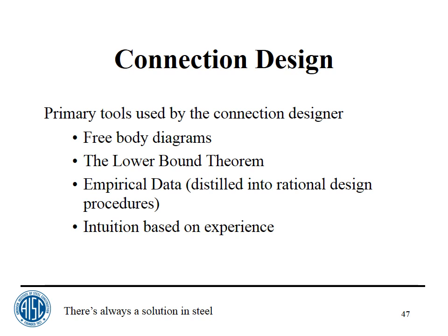So, connection design. The primary tools used by the connection designer are free body diagrams, the lower bound theorem, empirical data distilled into rational design procedures, and intuition based on experience. That first item there, free body diagrams. You'd be surprised how many engineers do not know how to do a free body diagram. You might say, I don't believe that. But we hire a lot of four-year graduates from really good schools, and we give them a little test to start to see how they do. And some of them really, even to do shear and bending moment diagrams, they want to use some computer program to do that. They don't want to sit down and draw the thing. To actually do a free body diagram.